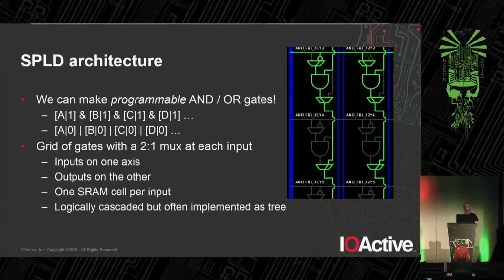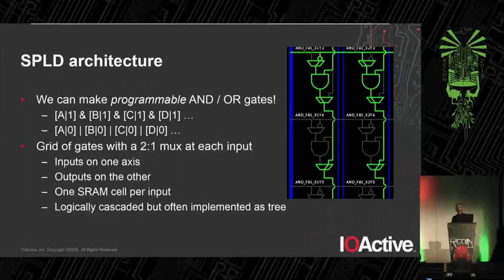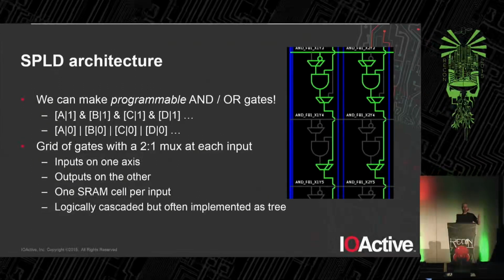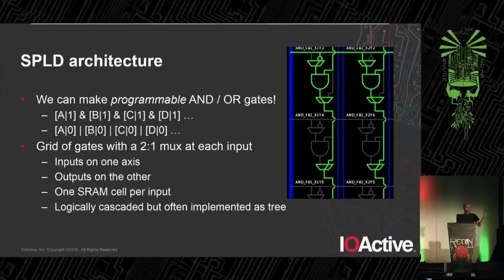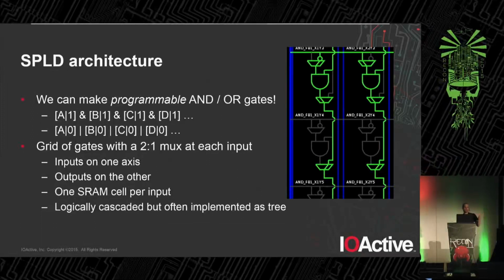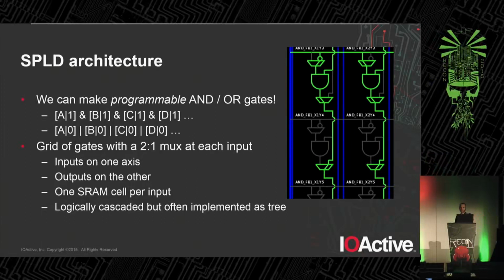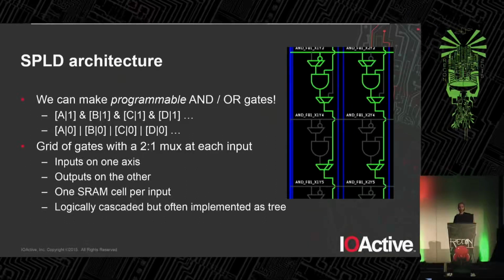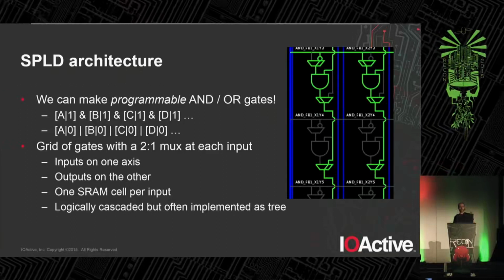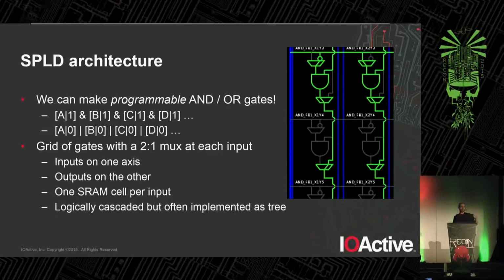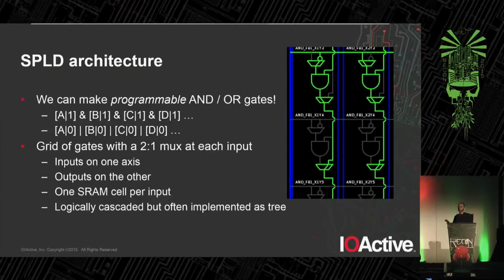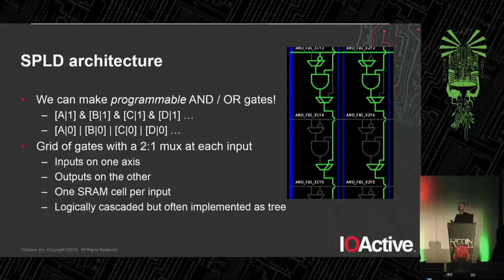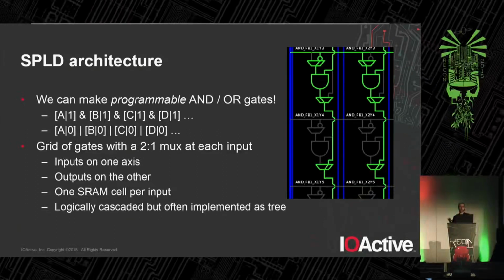So you can express any arbitrary digital equation this way. So let's look at how we'll actually make a chip to do this. If we have a large, say, 32 input AND gate, and we have a mux at each input to the gate that lets me select between a constant 1 or the input to my circuit, I can effectively mux any subset of these inputs and just leave the others as 1, which is the identity for the bitwise AND operation. So I can AND together any subset of the possible inputs to this AND gate.